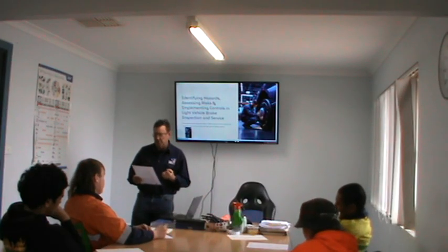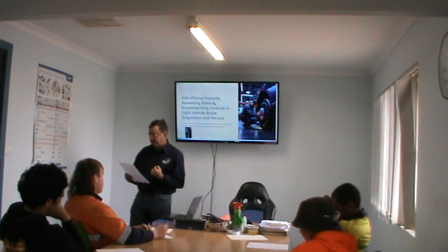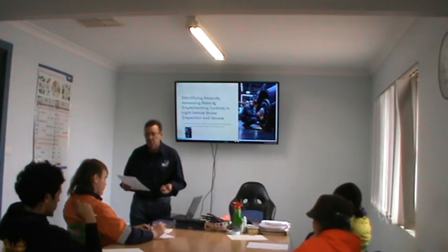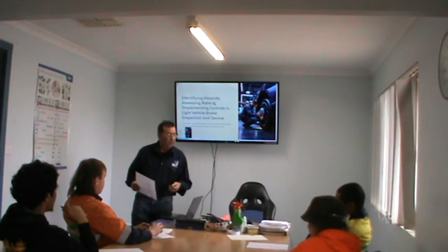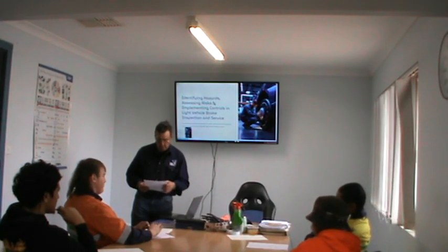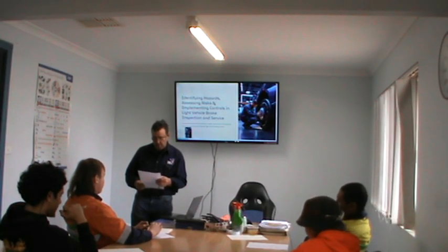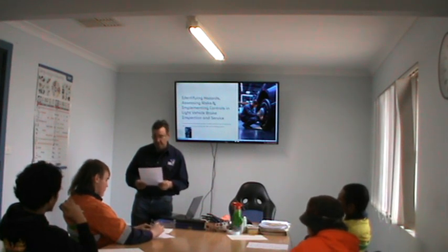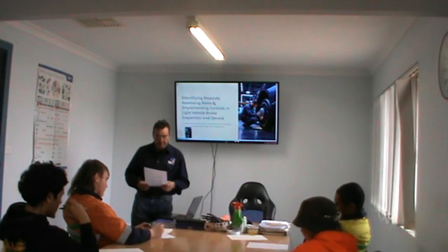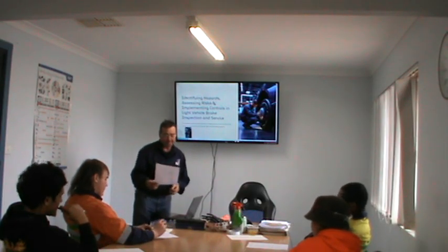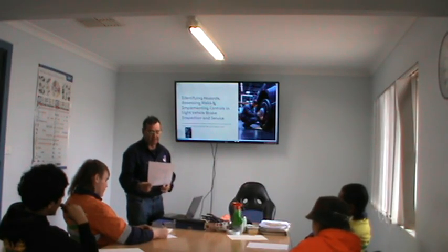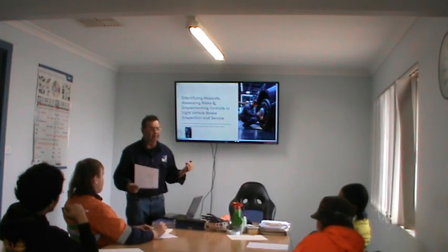What control measure should be used to reduce the inhalation of brake dust? Wet wiping the components, yeah. So we're not just going to blow it out. What PPE is most critical when inspecting brake fluid systems? Safety glasses, absolutely. You're not going to wear a welding helmet, are you?